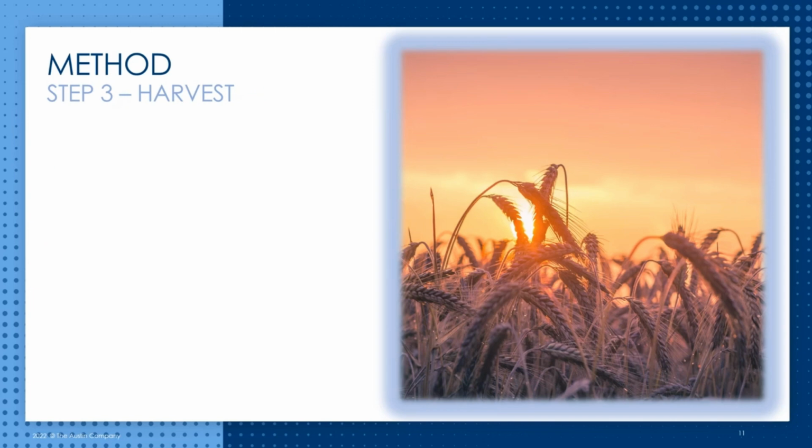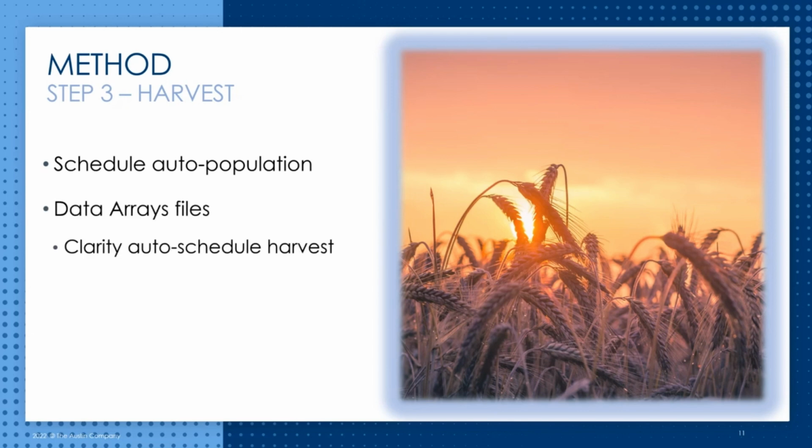Once the virtual model is generated and organized, the precious data which it contains can be harvested. In Revit, once a modeled element is properly labeled, it is automatically sorted within tables or schedules. These schedules can then be harvested as standalone files exported from Revit. Note that with the use of software such as Clarity, auto extraction of data can be scheduled monthly, weekly, or even daily. Finally, custom computer scripts can be written in languages such as Visual Basic and PHP plus MySQL to organize and place the harvested data into external databases.